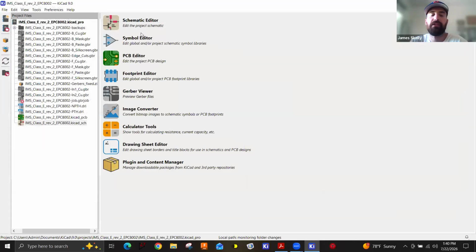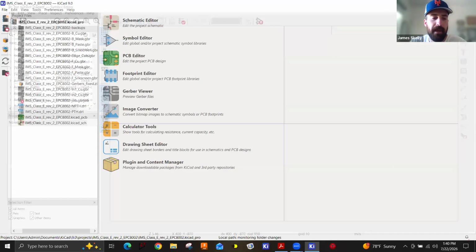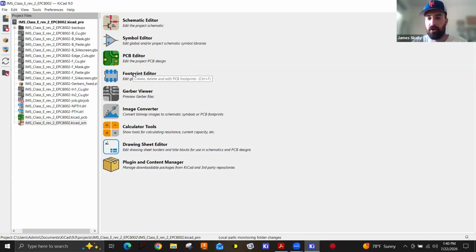Okay, so the symbols and the schematic are linked. Symbols go into the schematics. That's important. And then the PCB and the footprints are also linked, because the footprint is telling us what the actual, sometimes it's called a land pattern. I think I showed this in module 5 actually. The footprint is where the part that you're going to physically put on the board is going to sit. Like, where are you going to solder it? Because it needs to be soldered onto the board, right?